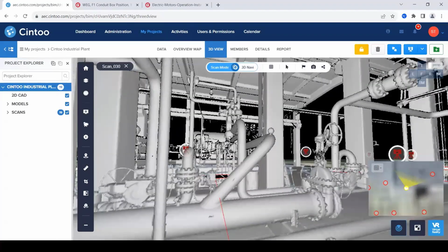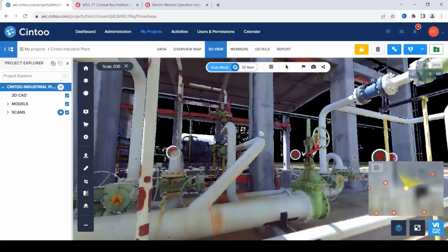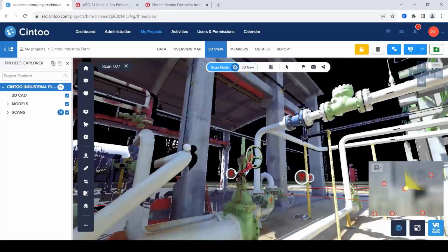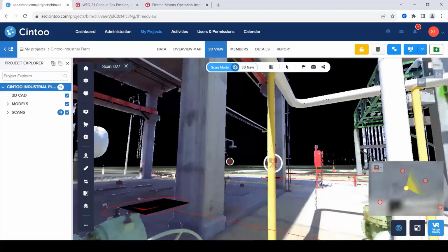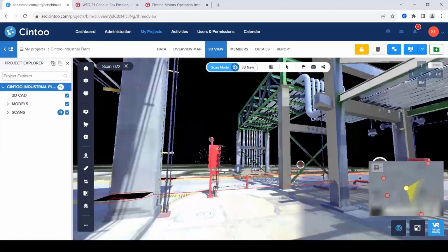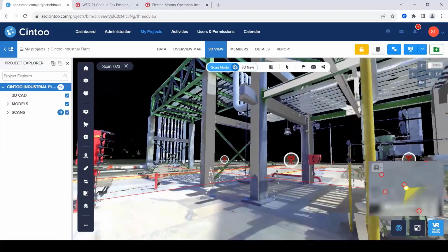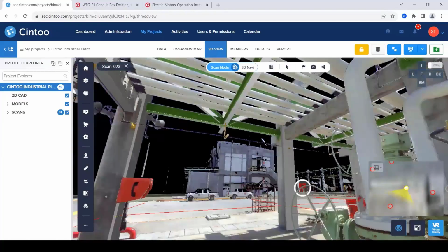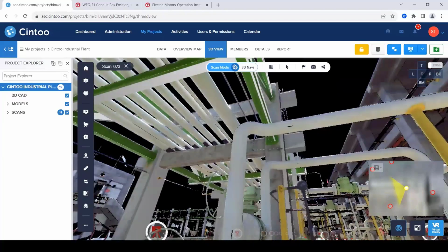And on top of this, you're able to click on display settings to click on 3D RGB, which showcases a colorized version of that solid surface mesh that we were just looking at, which is done by taking the color captured by your laser scanner and overlaying it on top of that solid surface mesh.